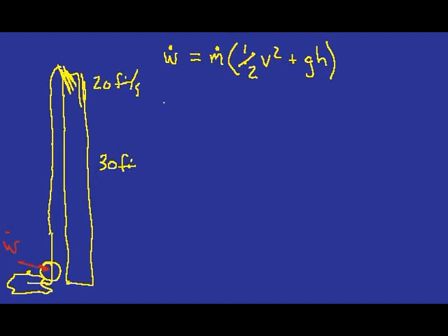So we take our units and put them in. We have, let's see, 3 horsepower. Now I'm going to convert that times 550 foot-pound force. And those of you in mechanical engineering will get to use foot-pound force quite a lot. 550 foot-pound force per second is equal to 1 horsepower. So that's per horsepower. Is equal to m dot